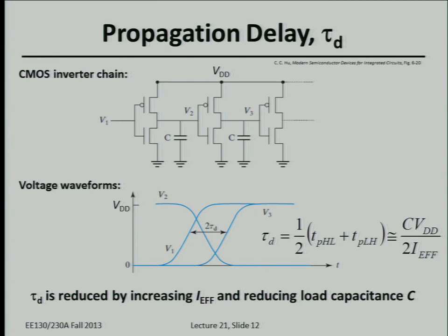No. Okay, so propagation delay. I just wanted to mention this load capacitance. We're just explicitly drawing it here. It's not something that we purposely add. We don't really ever purposely fabricate a capacitor right there at the output node of any digital circuit. But basically, it always exists. So where does that capacitance come from? That's the question. There are 3 different components of that load capacitance that always exist.